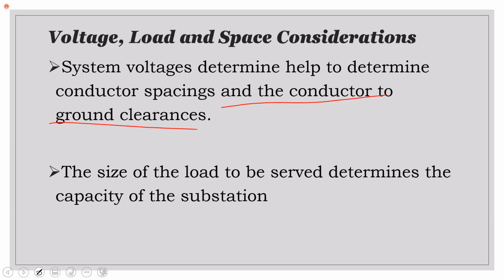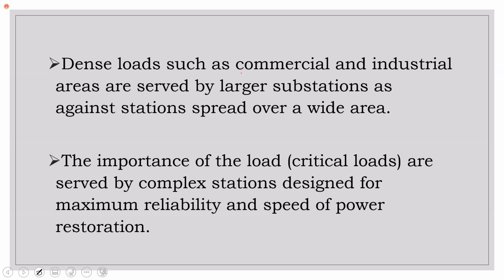Now, the size of the load that needs to be served also determines the capacity of the substation. Right? What is the loading? So you're going to buy your transformer based on that. Right? What kind of load are you doing? Remember I said earlier, and you see, I come back to that beautiful question from Ms. Michael. Because the type of load, whether it's commercial, industrial, or residential, yes, will dictate the sort of substation that I build.